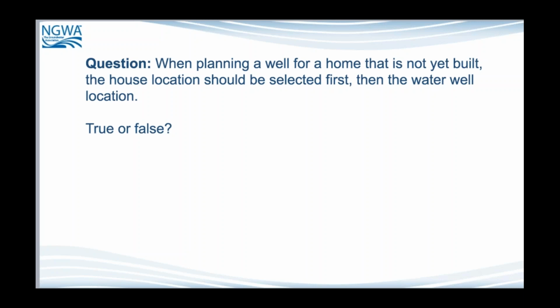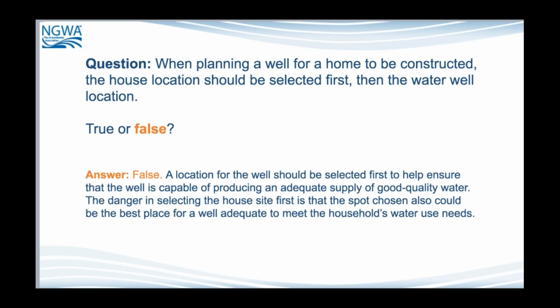So this is true? No, this is false. The water well needs to be selected before the house in most situations. The location of the well should be selected first to help ensure that the well is capable of producing an adequate supply of good quality water.